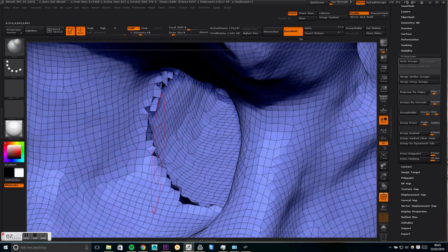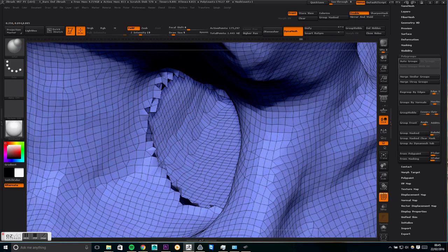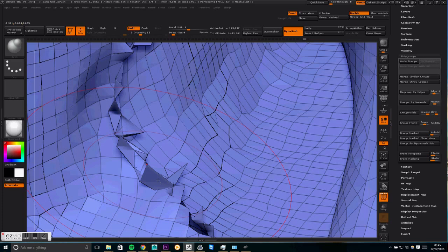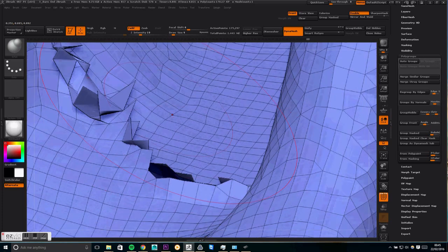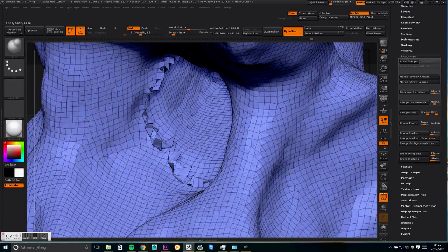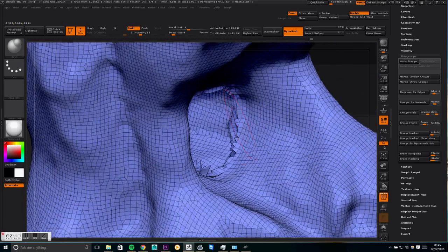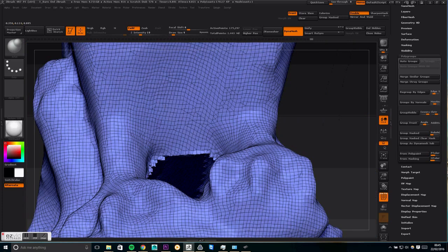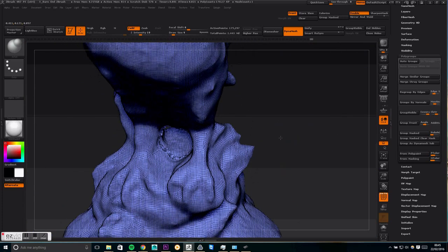So now the problem is, you see they're not part of the same mesh. They seem to be separate pieces. So to fix that, you need to go into the inflate brush tool and then just press Alt and just try and get the two pieces of the mesh to converge. So just do that throughout the whole of both of the sides of the model.